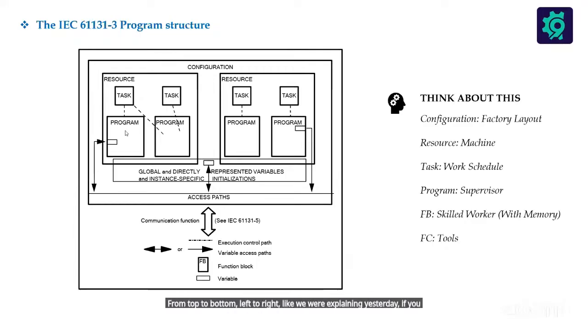If you are writing in ladder, when you call all your FBs and everything in your OB1, your OB will now check, let's say FB1, what's going on in FB1? Then FB1 will run all its program. When it's done, it will return back to OB. OB1 will run the next one, and that is how it goes. Your OB1 will manage all the programs that you have. So in this case, your OB1 serves as a task, that is the work schedule, and your program will be written inside your FBs. I hope that explains it.